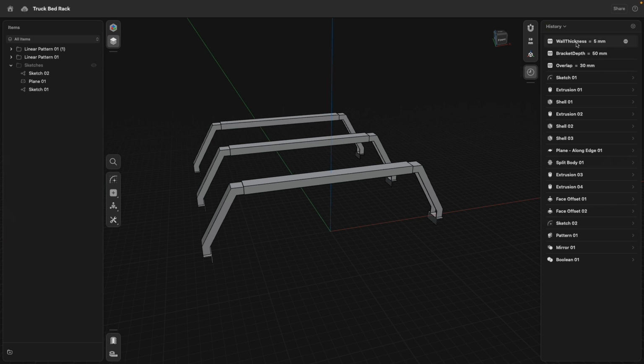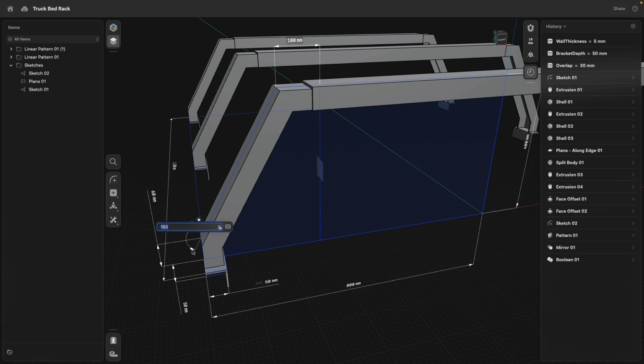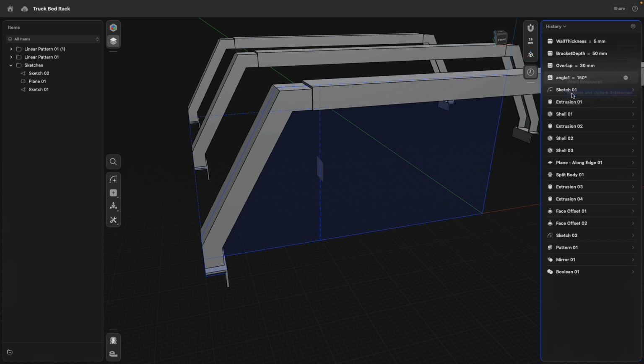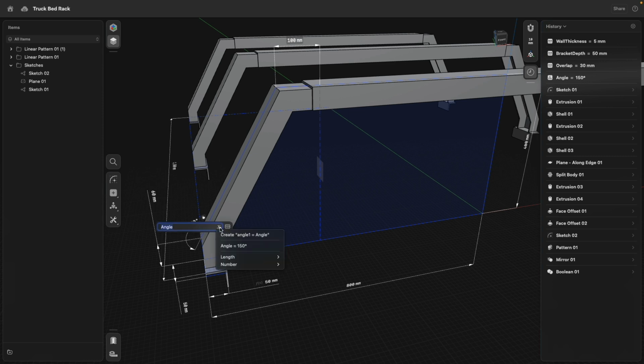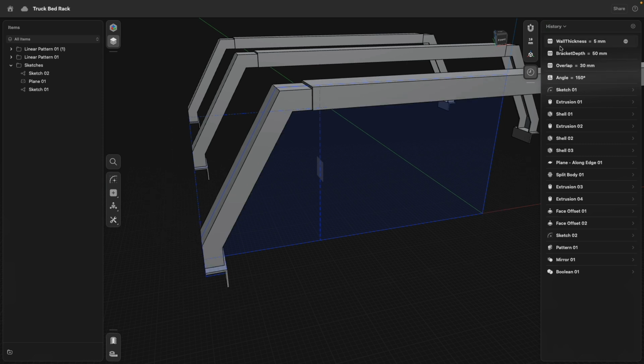I have here so far always like dimensions for like a length. I would like to go back to the sketch. You see here, this says 50. I could actually create also an angle. There we are. And right click and rename. I just keep this angle just so you see, I can then select different length or numbers. I only have one angle, but you see things are later also being sorted into different categories. So it makes it very easy to then, when you have to select those, to assign them.